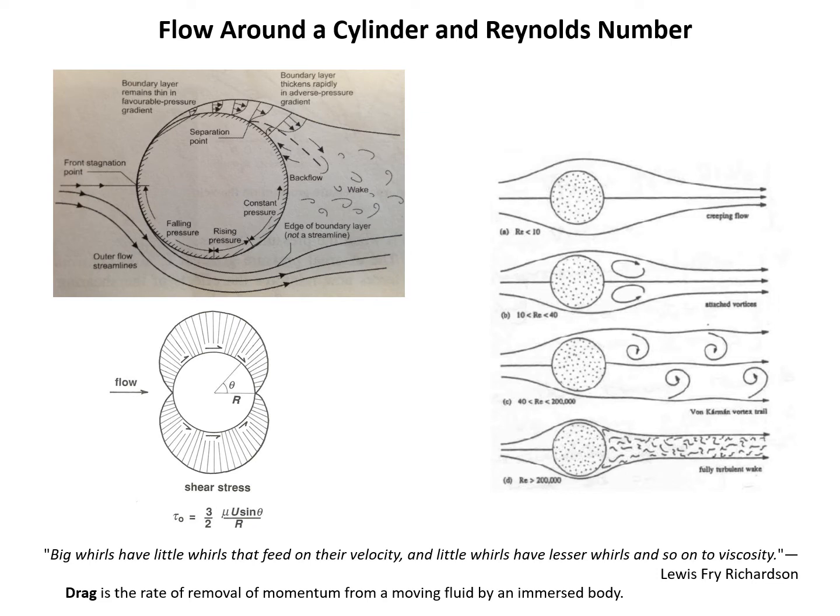And at even higher Reynolds numbers, turbulence sets in. You get a turbulent boundary layer. Now look at the difference between the thickness of that boundary layer when the vortices are being shed, and you've got the von Karman vortex street, versus once the boundary layer becomes turbulent. Now the wake is much smaller, and the system is actually losing less energy to those vortices.